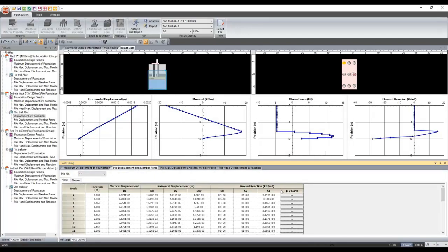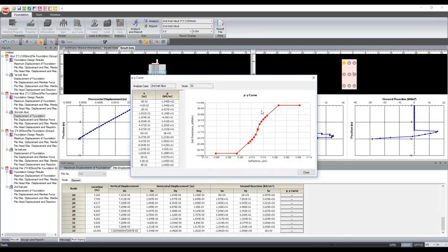So here the total length is around 10 meters. And what we see is that we got a different nonlinear spring when compared with the nonlinear spring of the 13 meter pile, because this 10 meter pile is resting in the weathered rock and not the soft rock. So that's why your nonlinear behavior is changed.